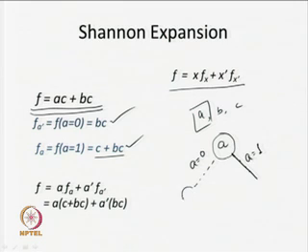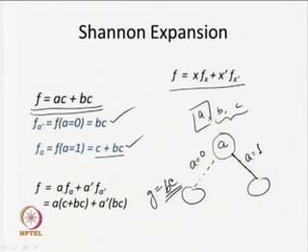So, what we need to evaluate is a function based on the variables b and c, because already we have taken the decision on a. Now, when a equal to 0, you see that the function will be b c. That means I am going to look at the function b c over here. So, I can say that this is your g, and when a equal to 1, I say that c plus b c is the value, and this is the function h. Now, my next task is to evaluate these functions g and h. Again, we will use this particular Shannon expansion.